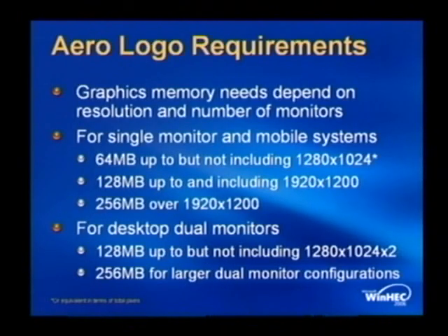Panels up to and including 1920 by 1200 require 128 megabytes, and panels larger than that really require 256. For desktop dual monitor scenarios, you essentially double everything, where you want 128 megabytes at dual 1280 by 1024 and 256 megabytes for larger dual panel configurations.